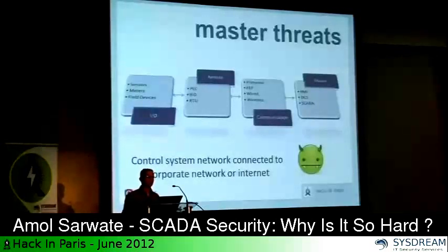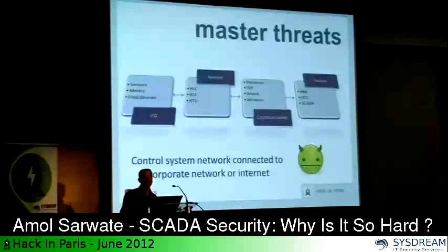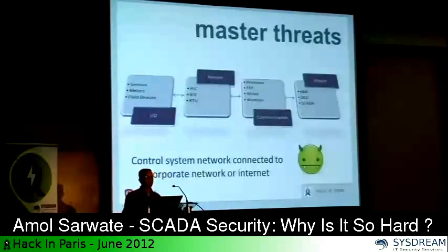So we looked at the physical threats in these SCADA systems, and communication threats. We did find a lot of communication threats. What we ended up doing was, if our scanner finds Modbus running or DNP3 running, we would say that, hey, you are vulnerable. You are running protocols which are not inherently secure. So make sure that you have other security processes in your network to compensate for that.